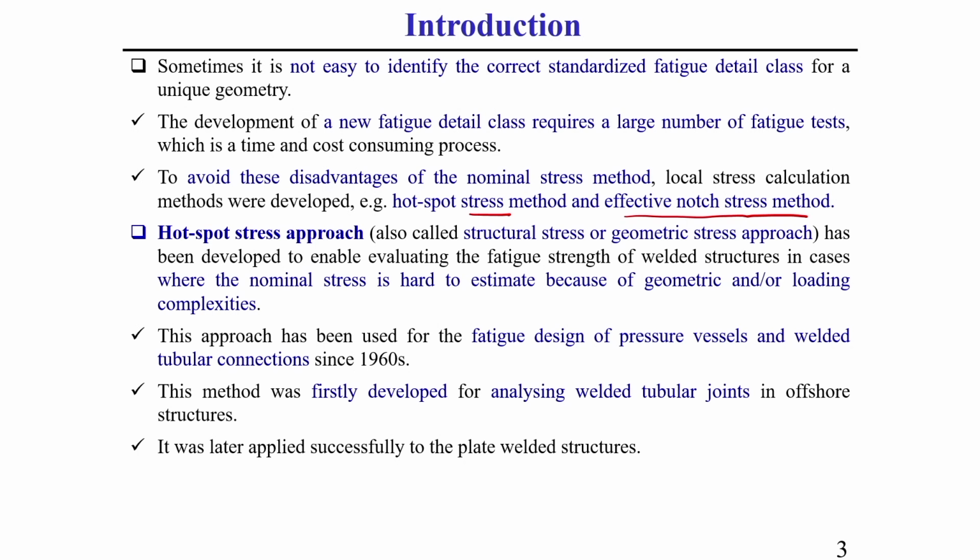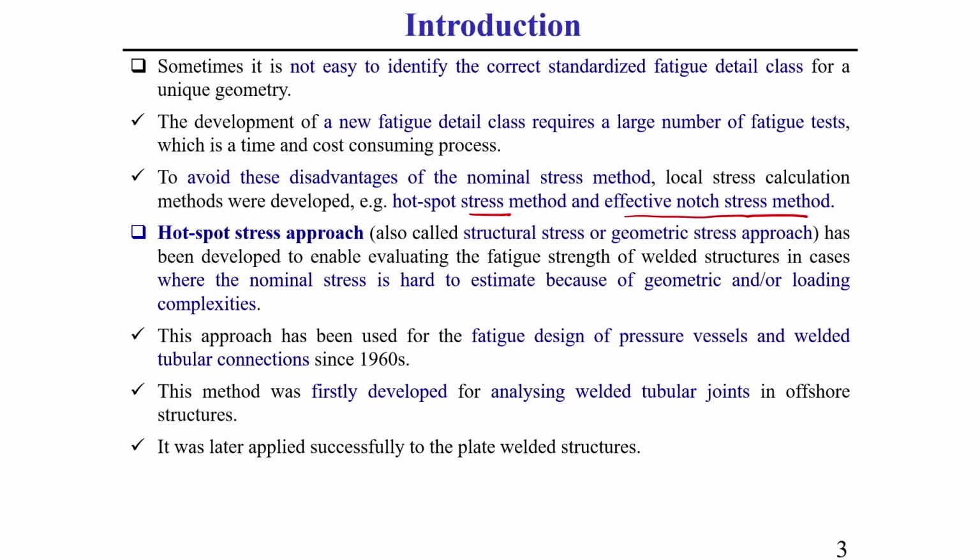These two methods are used instead of the nominal stress approach where the geometry is complex in nature and where the fatigue data or FAT class is not available. There we can effectively use the hot spot approach and the effective notch approach. The hot spot approach is also generally called the structural stress approach or geometric approach, you should keep this in mind.